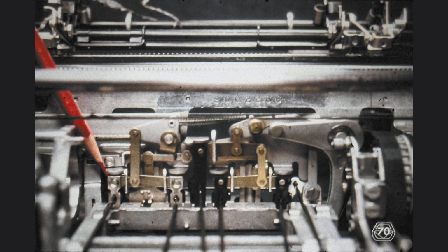Now cycle the T again and observe on your machine that the tilt bell crank rotates counterclockwise and pushes the tilt arm away from the power frame of the machine, with the end result that the tilt pulley is moved toward the left, away from the carrier. Moving the left-hand tilt pulley away from the power frame is really pulling on the tilt tape, and somebody has to give. We know that the right end of the tilt tape is permanently anchored to the carrier frame, but the left end of the tilt tape is connected to the tilt pulley sector on the rocker, and it will rotate when we pull on the tilt tape.